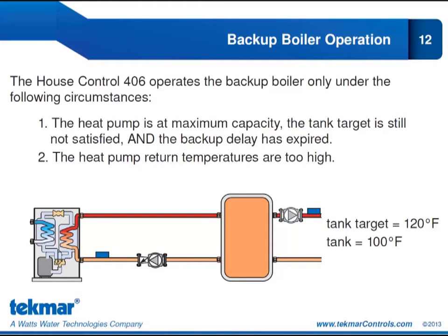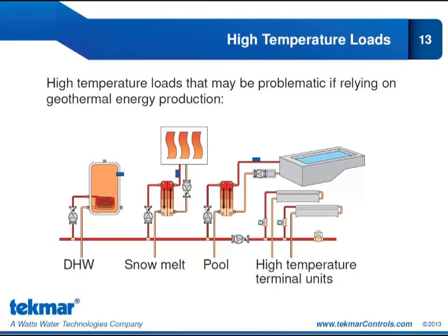Now we mentioned that high temperature loads can cause that tank target to increase beyond the abilities of the heat pump. So what are some high temperature loads? Here we have an image where we have illustrated a couple of high temperature loads. We have domestic hot water. We have a snow melt system. So here we have our supply water going to a heat exchanger, and the other side of that heat exchanger is our snow melt slab.